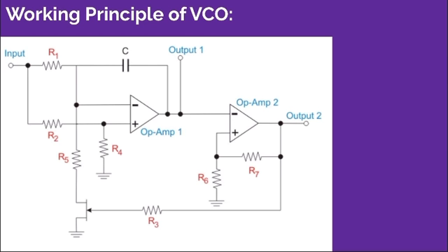Here, when the MOSFET is in on condition, the current flowing from the R1 resistor passes through the MOSFET. Here R2 has half of the resistance, so the same voltage drop and twice the current as R1. The extra current charges the connected capacitor. So the operational amplifier 1 should provide a gradually increasing output voltage to supply this current.